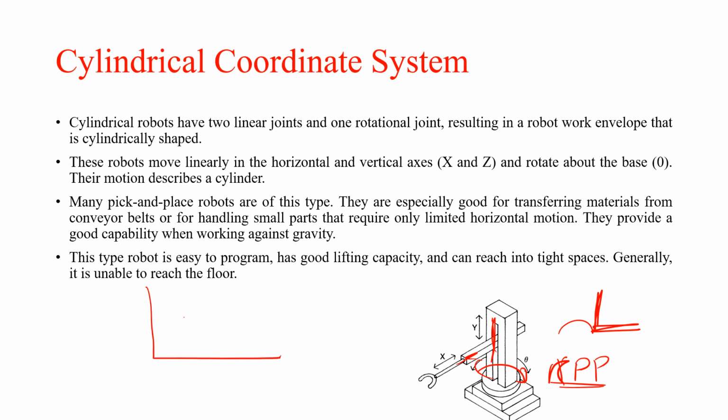For example, you take a board. Here I have written something, and I have to use a duster. That duster should run, but it should work autonomously. For that purpose, first you assume the duster moves in this direction, the y direction. So that is 1 degree of freedom. If you use only this direction, only this portion will be erased, but this portion will not be erased. So you make the robot move in this direction also. So one more degree of freedom, this is the y direction and this is the x direction.